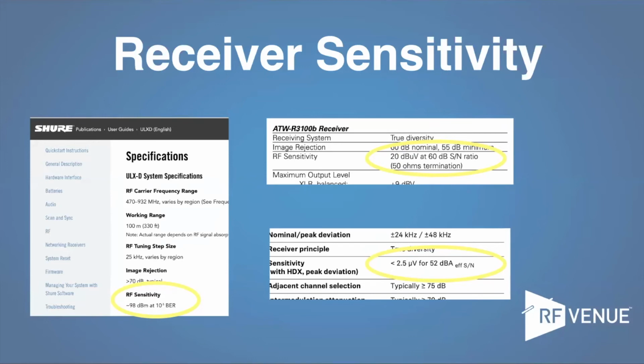These all say the same thing, but none of them look the same. I'm not saying these are all identical, but what this tells you is a level, a voltage level, a power level that needs to come into the input in order for the radio to push the signal above whatever they consider the noise of their own radio. Because if it's buried in the noise, you can't hear it. Even if you're testing your system, you're running pink noise in the auditorium, you can't talk over that.